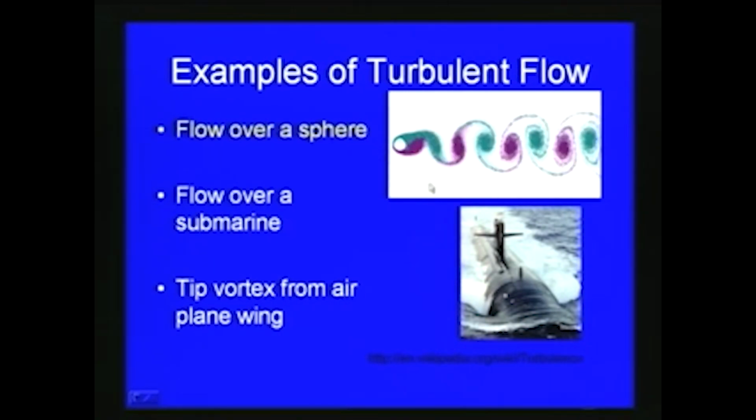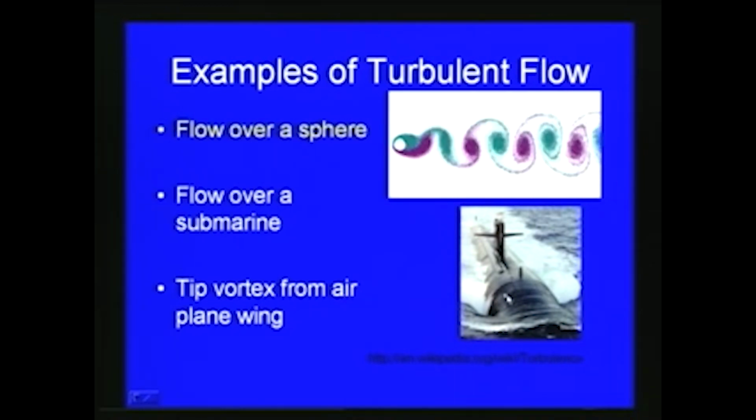So, then the flow comes and turbulence is generated. Here you can also see a submarine. Due to the presence of a solid wall, whenever turbulence is generated, that turbulence is called wall turbulence. One of the important reasons, as we have seen, is the presence of a solid, that is, fluid structure interaction. So, this is one of the important categories of turbulence, wall turbulence.